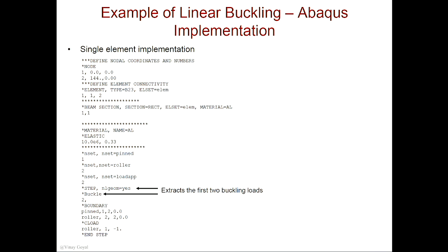Yes? Can you explain that again? So do we always define it as 1? You can define it whatever you want. You can make up, give me a number. 10. Say it's 10. I put a reference value of 10. Then the eigenvalue you may get is 100 if the buckling load is 1,000. Okay? Is that clear? All right.